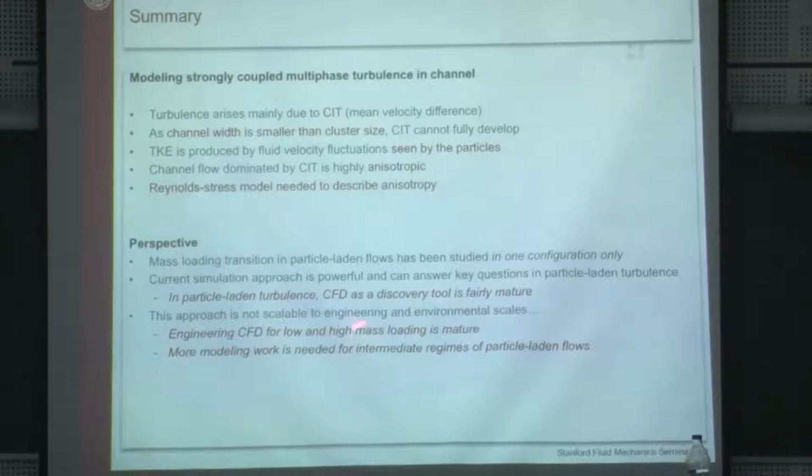For high mass loading flows, we've discussed a number of things that work well as well, but it's more difficult. There are a lot of modeling questions. You find out a lot of fluidized bed reactors are being designed today using K-epsilon type models. We think it's bogus. I don't think this is something that can be done in a reasonable way.